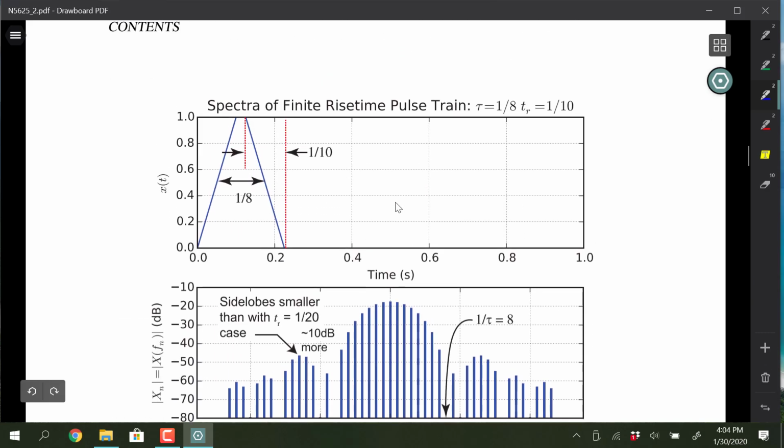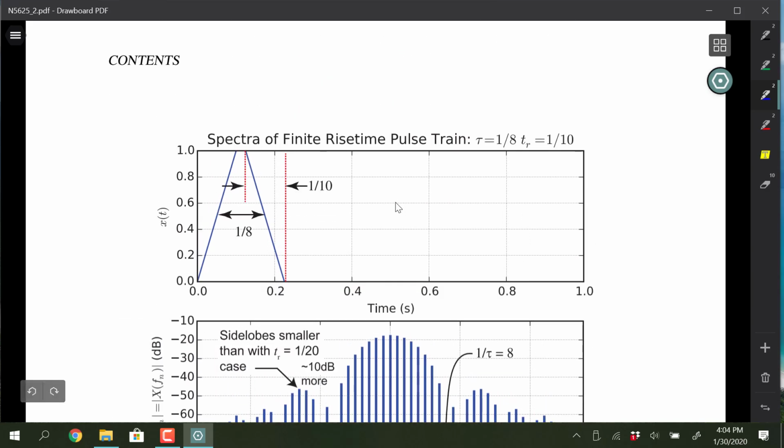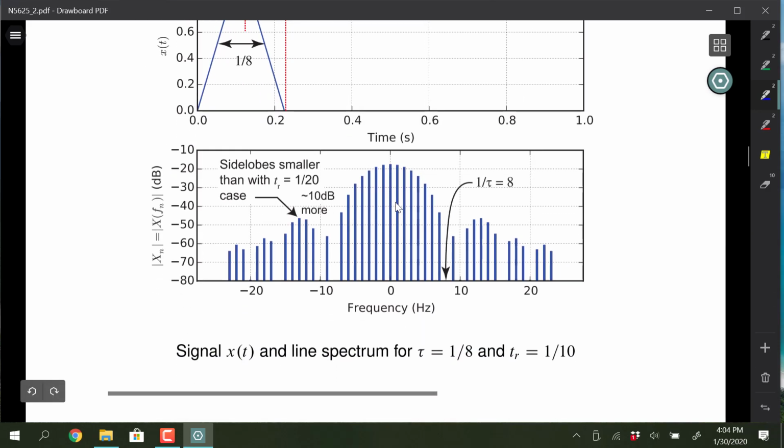And then I took a second kind of really extreme example, and this would be a scenario where you might increase the clock rate, and now the rise and fall time is really, you're pushing the limits because the logic family is getting close to its maximum clocking rate because it has rise and fall time that's limiting the ability to discern ones and zeros. So here, the side lobes are even smaller because the waveform is spending more time rising up and falling down.